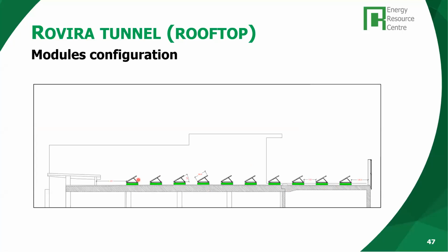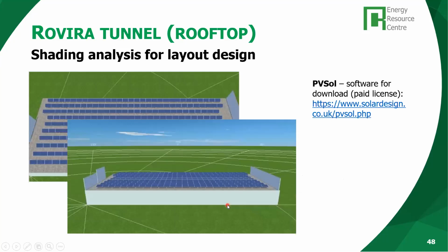Yes, for instance, I know in some projects in the Arab countries, in the Arabian Peninsula, very hot, with very high temperatures, 50 degrees and higher, some PV systems even consider some kind of refrigeration, some forced ventilation behind them. So you use part of the electricity they generate to try and ventilate the modules, okay? Because of this effect.